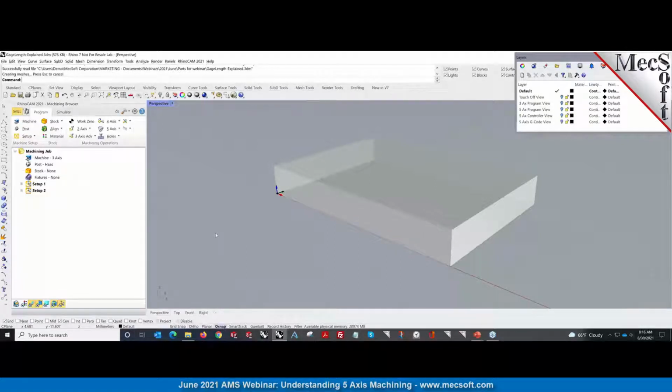We're looking at it from a machine viewpoint. And in most cases, with the machine coordinate system, or the way the machine is set up, the X, Y and Z axes of the machine will coincide with the design coordinate system. So here I show you the world coordinate axes that our CAM system is displaying, and as you can see, they're parallel to the design system. So everything is fine and good here. In most CAD systems, this is the case. The world coordinate system coincides with the machine coordinate system, and so you don't have to do a lot of mental gymnastics to figure out where you're machining.